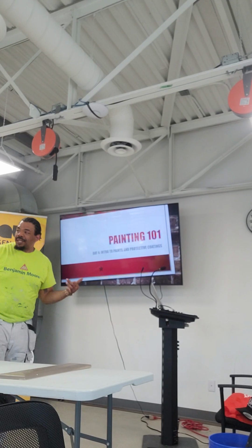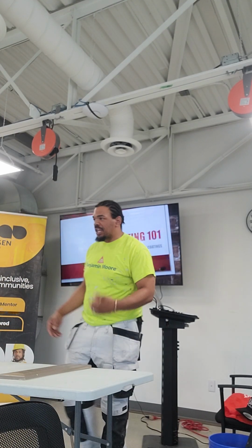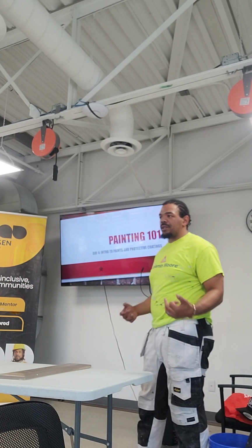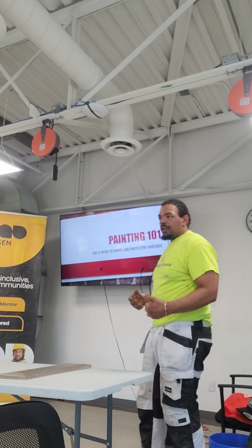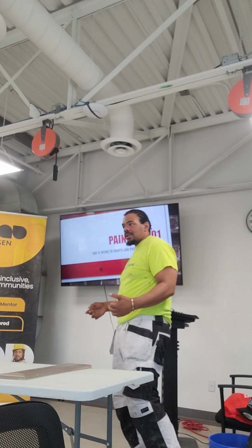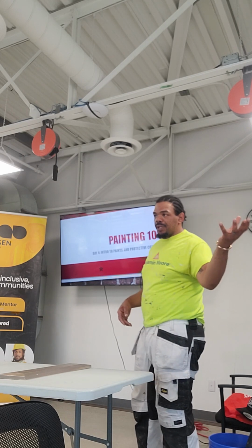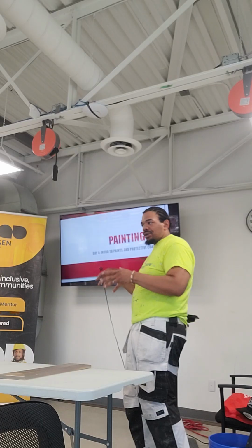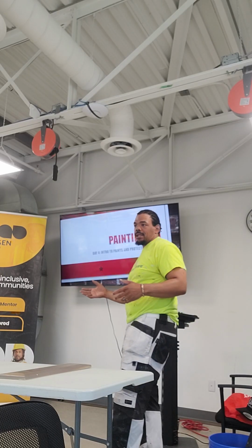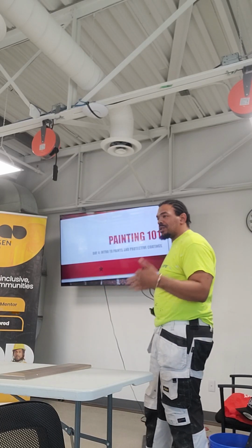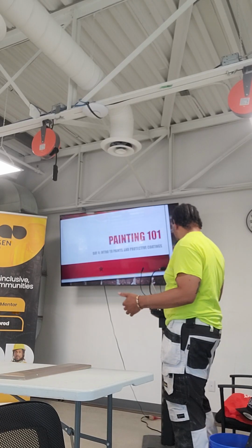So we're going to go through some of the science behind the top coat. Not just theory, but we're going to talk about how some of these products that we use are actually made, the chemicals involved in it, and the processes it takes for them to go from being in a can or being in the natural mineral state to being synthesized and turned into a material that we use for painting. Okay? So today we go into the science of paints.